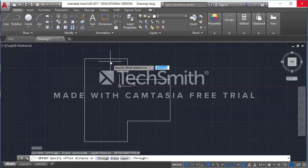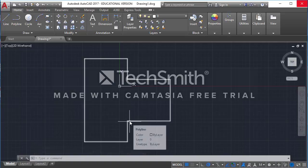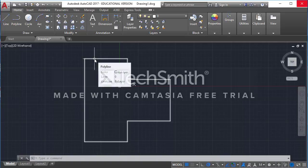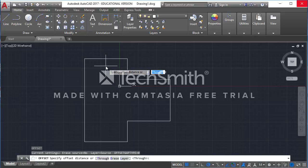Now we have the perimeter of our building, okay? Right now it's just represented by a single polyline, all right? So we need to give our wall a little bit of depth, okay? We all know that walls have some thickness to them, right? So if I type in the command O, which stands for offset, I can go ahead and hit enter. And the next thing that it's prompting me to do, here and up there, is to specify the offset